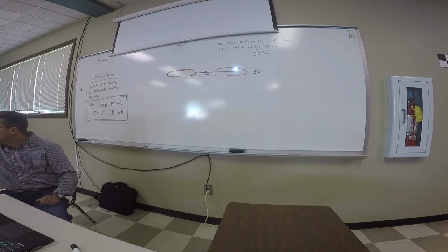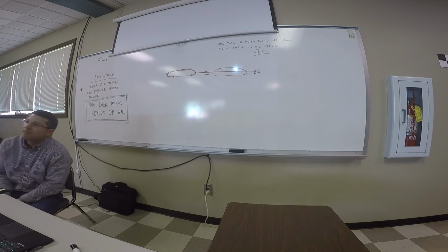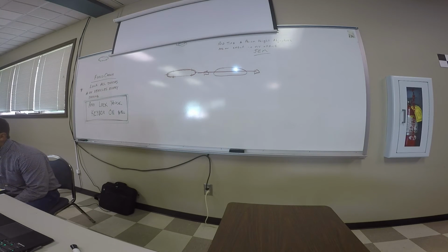NE codes. What gets an NE code? Reflectorless shots, and you're not doing building height. If you're going to shoot a building height, obviously building height has a code for itself. You don't have to use NE on a building height. We have a building height code. Was it BHGT? Mm-hmm. That code alone tells us, and we put finish 4 later. We freeze that before we run topo or anything with vertical.